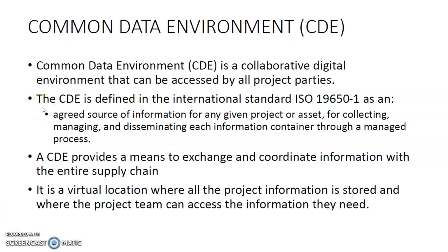So this common data environment, in short we call it CDE. CDE is a collaborative digital environment that can be accessed by all project parties. And CDE is defined in the ISO standard 19650, which we talked about in the previous lecture, as an agreed source of information for any given project or asset for collecting, managing, and disseminating each information container through a managed process. A CDE provides a means to exchange and coordinate information with the entire supply chain.